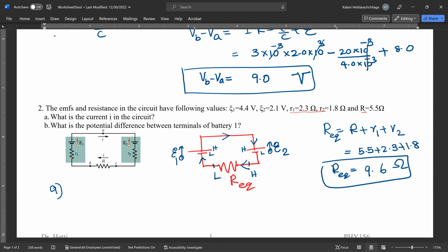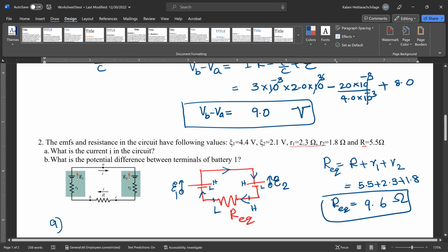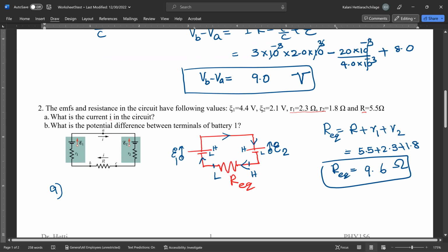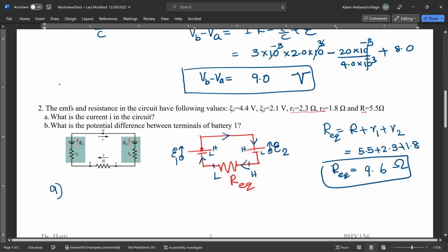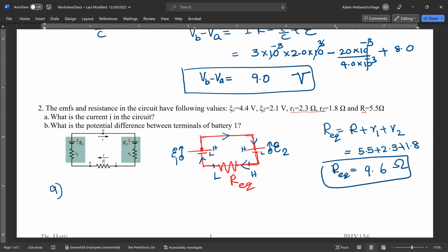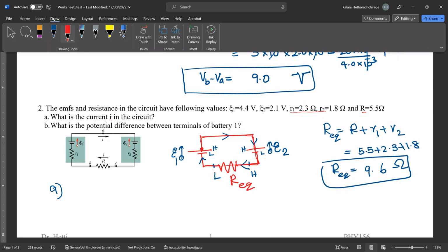After you identify that, this is actually what we call the potential difference rule. We're going to explore more in your lecture number 6. But let's start at one point, and we're going to walk through the circuit. That's what we call the potential difference rule. We're going to learn more about that in your lecture number 6. But let's start from here. We already know the potential at this point. You're going to walk through this circuit in the counterclockwise direction, starting from epsilon 1.